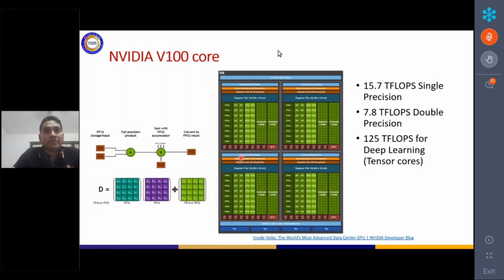Now, why is matrix multiplication necessary, and why are we calling them tensor cores? These tensor cores are designed specifically to run AI benchmarks, which are deep neural network based or convolutional neural network based, to be precise. These convolutional neural network computations need a main engine, the convolution engine, and the convolution can be interpreted as, or converted to, matrix multiplication.